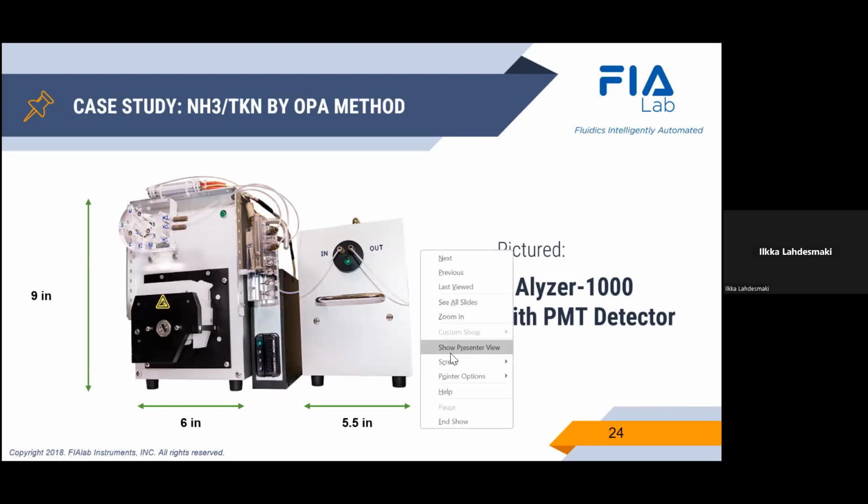And let me see, on this slide you can see, let me bring back the laser pointer again so that I can highlight. Here is the gas diffusion block, and this curved metal part is the lever that I was talking about. You would just lift this up, then slide this top block off of its rails. The rails are these metal parts over here. So the top block slides off. That gives you access to the membrane. You peel off the membrane, put a new one back on, slide the top block back in, then slide in the lever and close the lever, and you're in business.